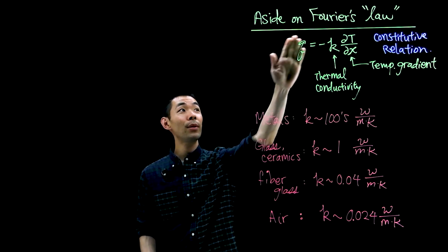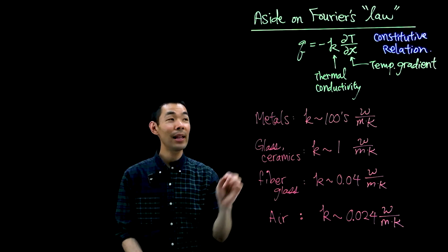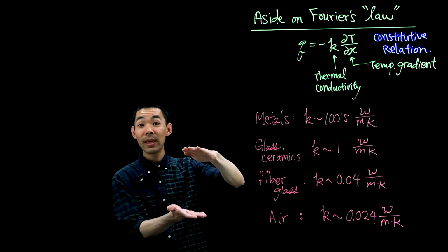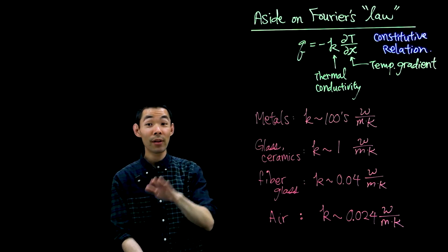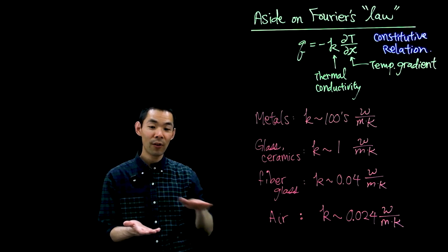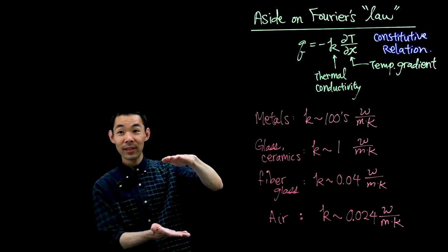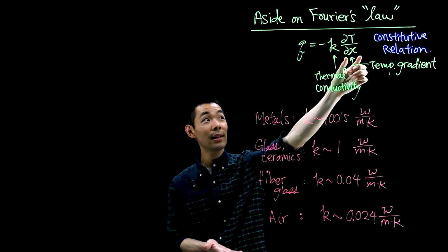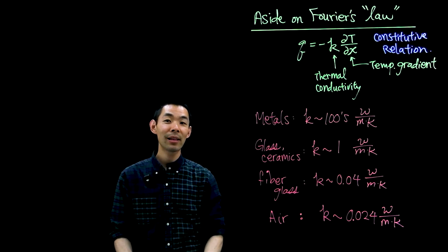Because our body perceives the heat flux, that's what matters. It's not really the temperature gradient between your warm body and the floor that's making the difference. It's, in this case, the thermal conductivity difference. The thermal conductivity of the carpet is much, much lower than the thermal conductivity of tile. And therefore, even though the temperature difference is the same, your foot is still at 37, the carpet's at 25 C, it's still the same partial T, partial X, but the K, the thermal conductivity, is different between the two materials. And that's why the kitchen tile feels cooler.